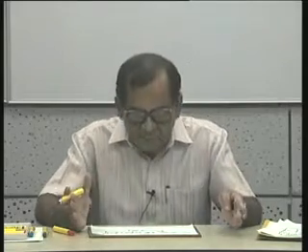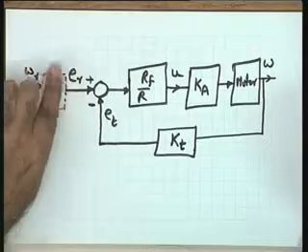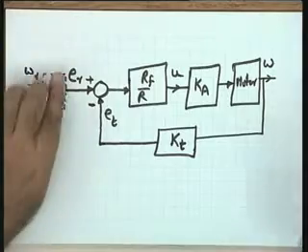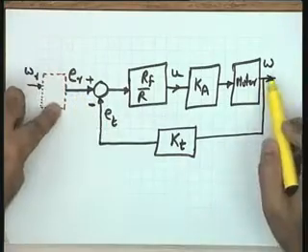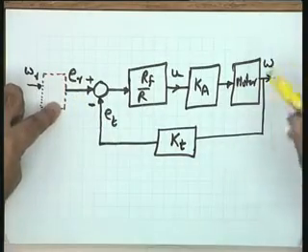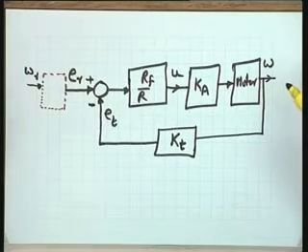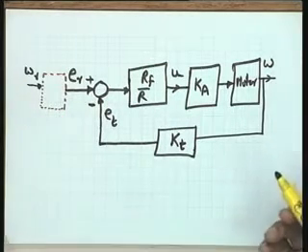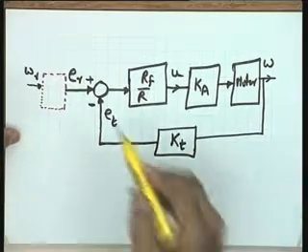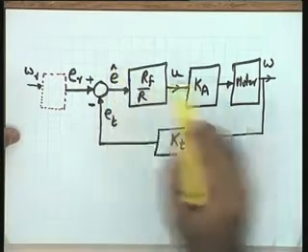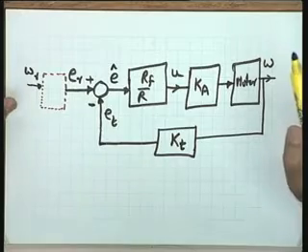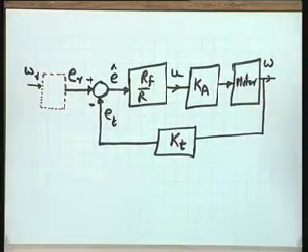But before we go to the motor block, let me look at this block diagram with respect to the general feedback structure which was given to you. Tell me please, this dotted block does not contain any physical component. If you look at the diagram from ER to omega and a feedback loop, it is a non-unity feedback structure. Naturally, in this particular case, there is a sensor transfer function, and you are going to have the actuating error signal, and this is a non-unity feedback structure.